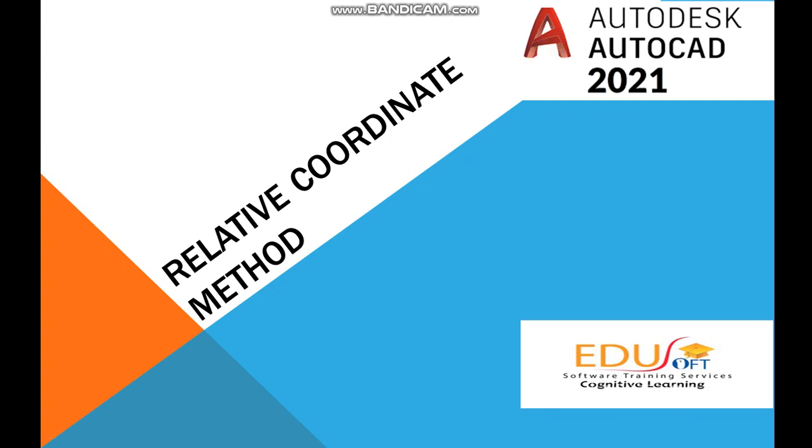Friends, today we will discuss the relative coordinate method to draw or modify geometric shapes and lines. Last class we saw the absolute coordinate method, where we gave the real x and y coordinates. In this method, we give the distance moved in the x and y directions respectively.